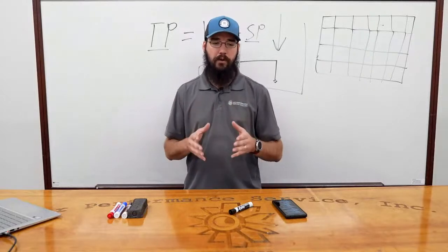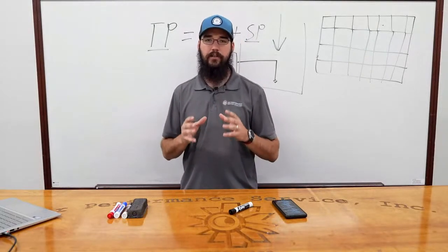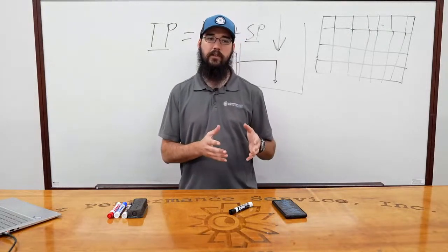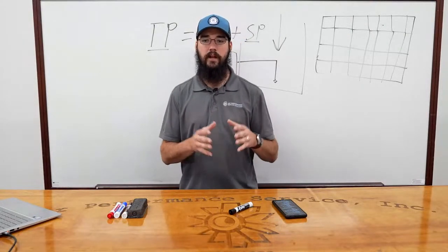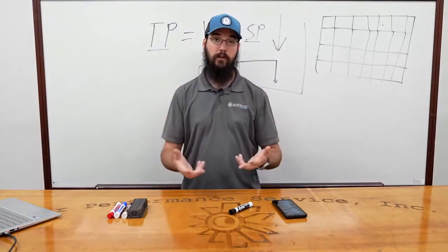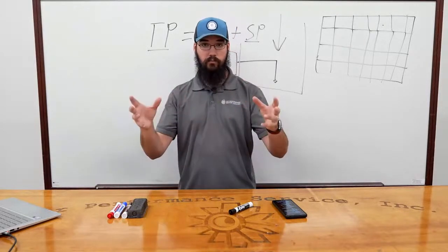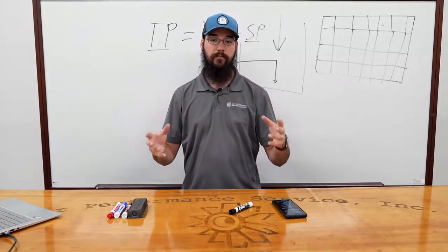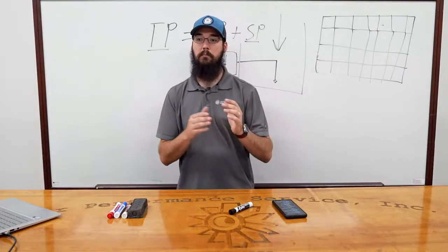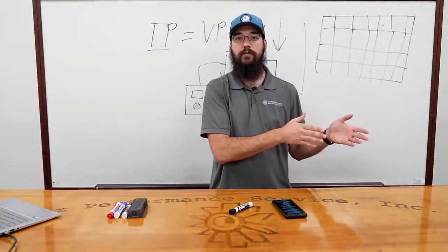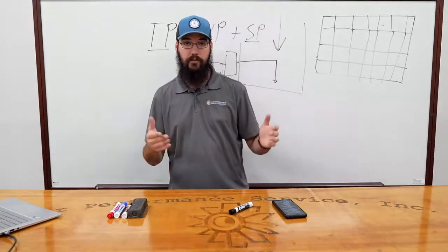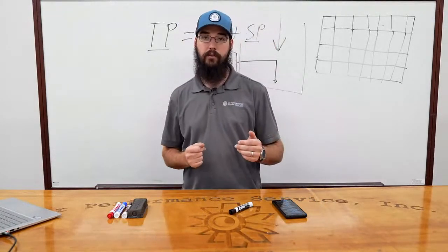In my personal opinion, there are a lot of readings that make a lot of sense. For example, if I see that there's a question on the airflow side, as soon as I hook up and get my superheat, my subcool, and my saturations, that's one of the very first things a lot of us do. As soon as I get that and I see those lower readings, my first go-to is to verify what my airflow looks like. And external static is a quick method of accomplishing that.